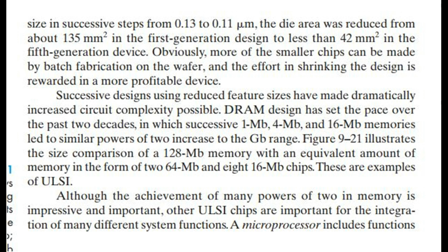Obviously, more of the smaller chips can be made by batch fabrication on the wafer, and the effort in shrinking the design is rewarded in a more profitable device. Successive designs using reduced feature sizes have made dramatically increased circuit complexity possible.